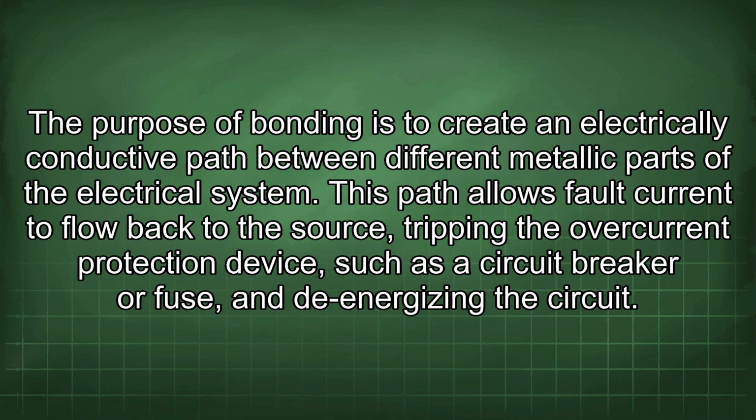The purpose of bonding is to create an electrically conductive path between different metallic parts of the electrical system. This path allows fault current to flow back to the source, tripping the overcurrent protection device, such as a circuit breaker or fuse, and de-energizing the circuit.